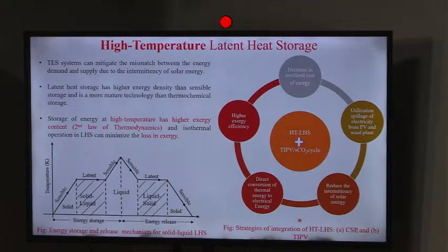Now, if I'm speaking about a system which is at a very high temperature compared to your room temperature, say 30 or 25 degrees centigrade, the amount of energy which you can extract from that high temperature system will be much higher in comparison to a system which is much closer to the dead state.